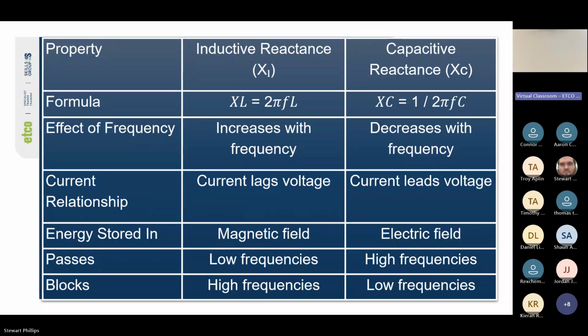So we will look at it in later lessons because we'll look at power factor. But if we get to a power factor of 1 or a balance between our capacitive and inductive components, we get what's called resonance at unity, which can lead to all kinds of nasty side effects, including the possibility of things going very, very colorfully red and exploding into many pieces. So that's the danger of having a power factor of 1. The most you want to get is to like 0.95.